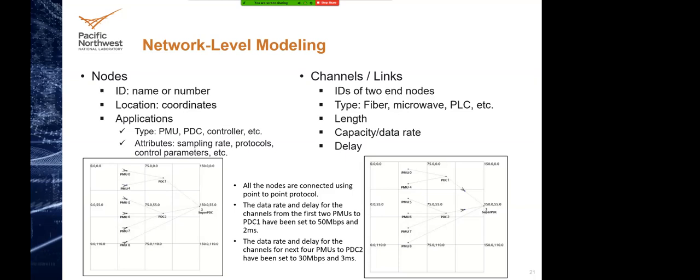It can be used for different applications like RAS, a control application which is very tightly dependent on the time delay and the data flow between the network and the RAS application. Then there is oscillation monitoring, where we are monitoring the frequency difference, as Dexin showed in the demo. All these things we can use this for, and we can make suggestions in the planning phase, like where we should place the PDC or PMU, what the network protocol should be, and the type and capacity.